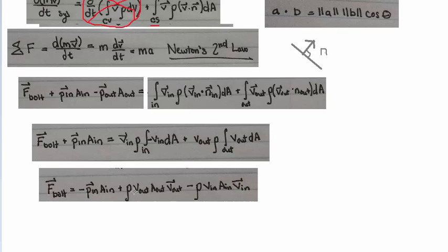Notice we have a scalar velocity and a vector velocity, and over here we have a scalar velocity and a vector velocity. That's necessary because we need all of these to be vectors to be dimensionally homogeneous. Again, you can't add vectors and scalars. You need to add either all vectors or all scalars. The reason I like to keep things in this form, rho v A v, is that you can see your transport definitions that are important directly out of here.